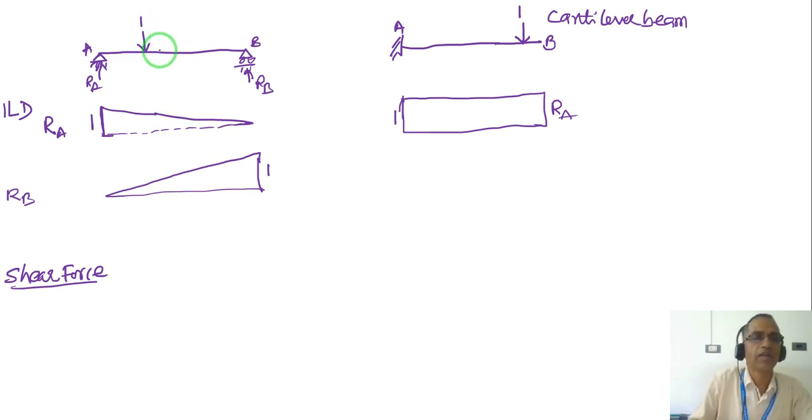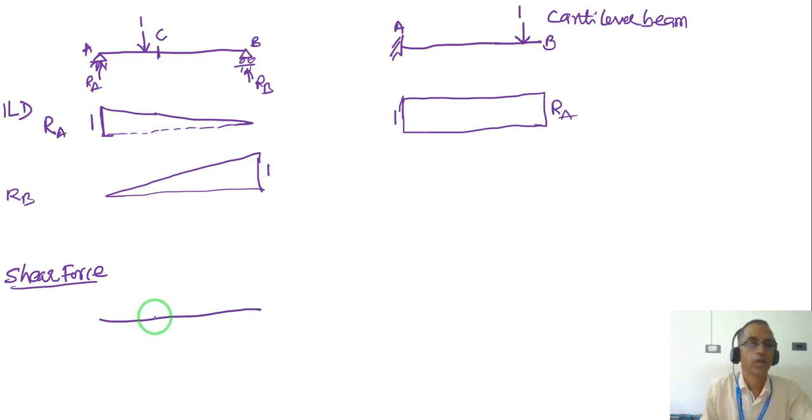So let us say I will take a section on a simply supported beam, that is a point section C. At that point I will have to draw something, a shear quantity, right? Something like this, the shear force applied. So then obviously the beam goes something like this. That means a unit shear has to be applied at the section where we want to find the shear force.